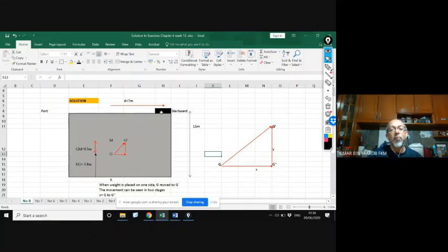And if you remove weight from here, G will move away from that point of addition. So in this case, you add, so it goes to G dash here. The question asks how far from the center line is the G dash and how far high it goes up, because it asks to find the location of the final center of gravity.